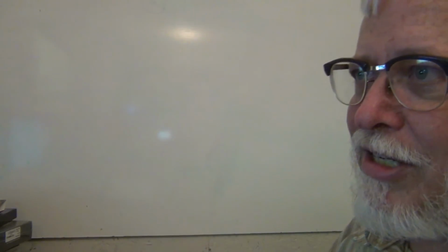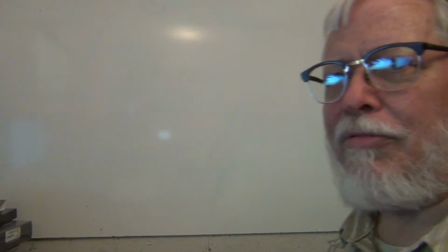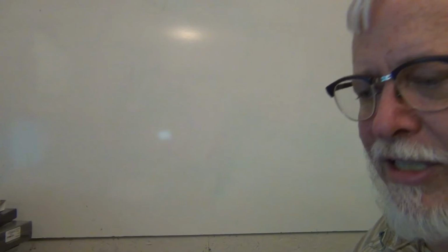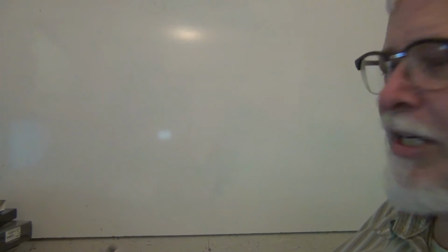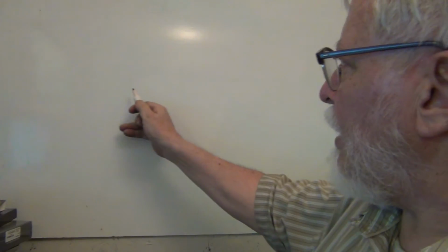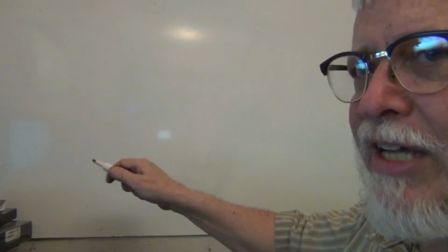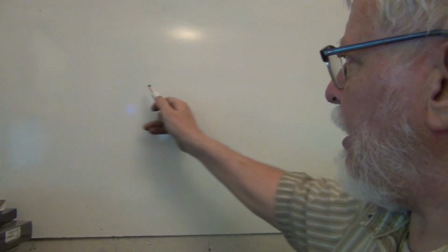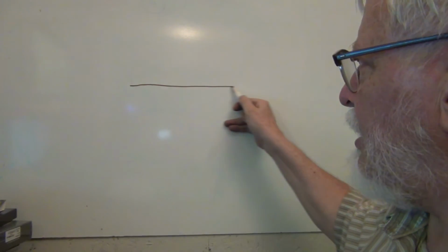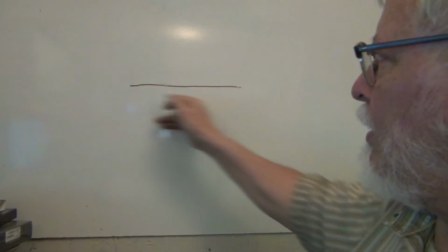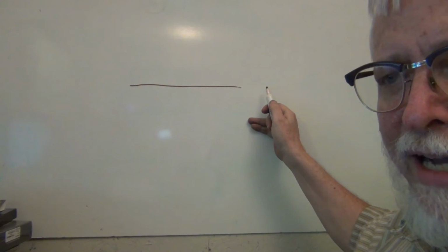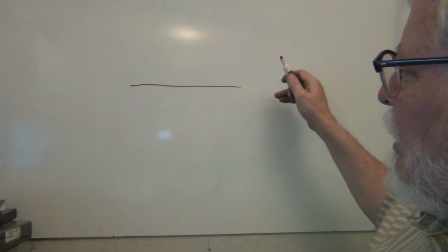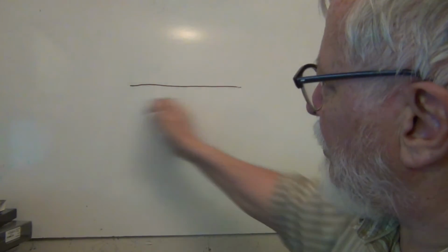Digital TV, it's all different now. It's all ones and zeros. But back in the analog days, the way television worked is you had a very fast ramp that went from 0 to, say, plus 10. And what that did is that it deflected the CRT's beam from the left side of the screen to the right side of the screen. Then it blanked off and did what was called a retrace.